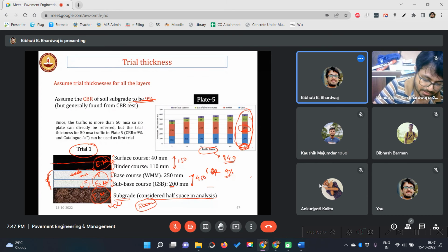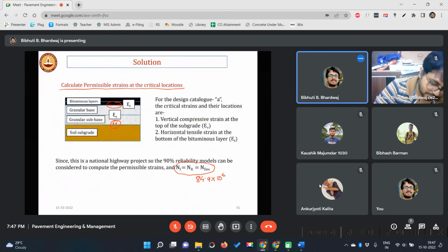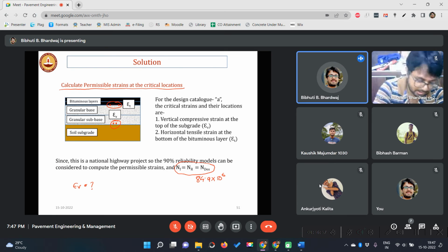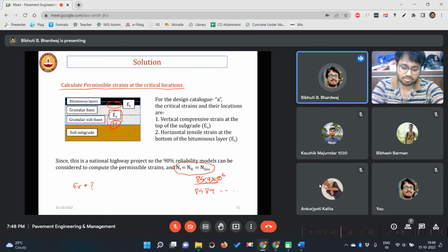You will tell me first. What is epsilon V? It means the maximum permissible vertical compressive strain at the top of the subgrade. Sir, since we're taking MSA, we have to multiply by 10 to the power 6. No, I told you, you take the accurate one. Don't take it like this. You got 8489 something, no? Take that as it is. Okay.